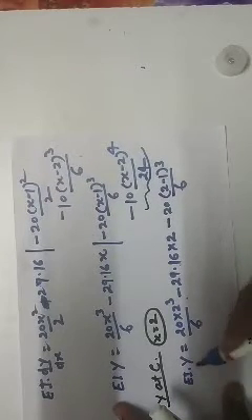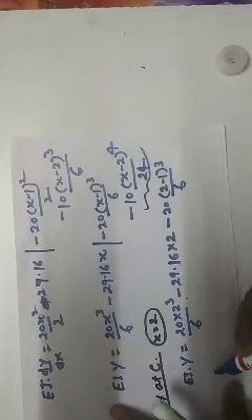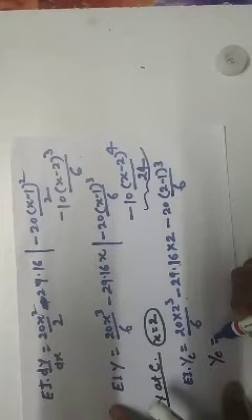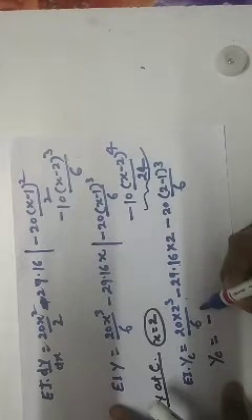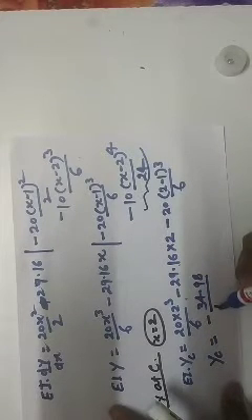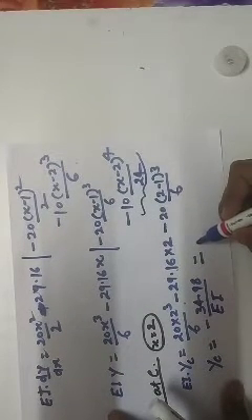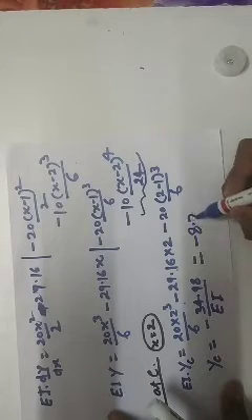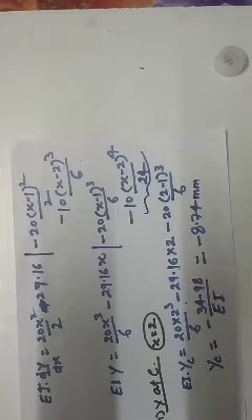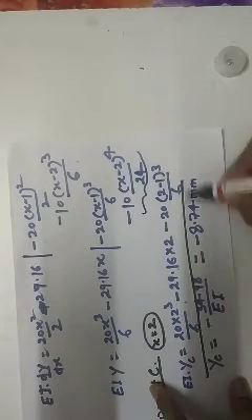Now simplify it and put the value of EI into this equation. When we simplify, we will find that yC will be equal to minus 34.98 upon EI, and EI is given. When we simplify, the value will be minus 8.74 mm. This will be our answer, right? So do the simplification and find the value.